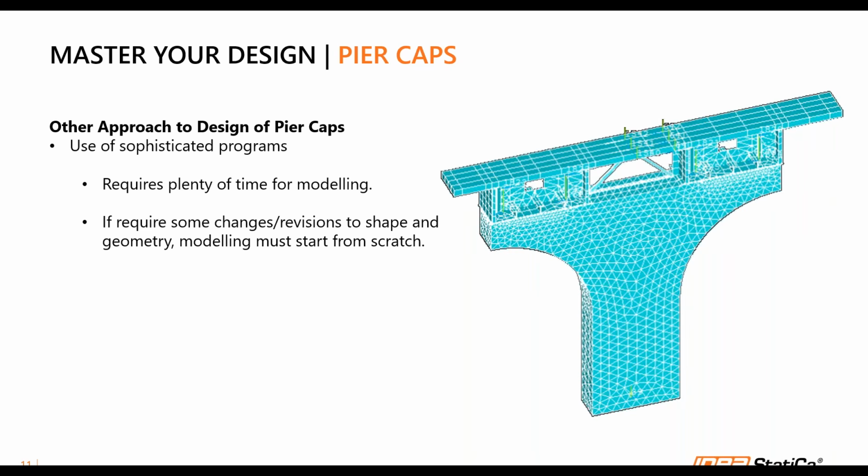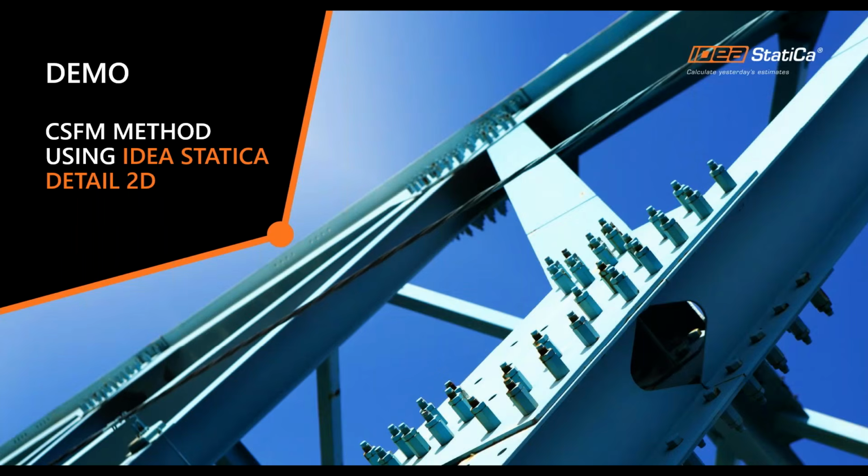And yeah, sometimes, if you have changes or revisions, for example to the shape and geometry, in some programs you may even have to start from scratch. So another alternative is the use of the CSFM method. In this demonstration, I'm going to show how to model and code check a Pier Cap using Detail 2D in IDEA StatiCa. We will model it together with a DXF file, as I mentioned earlier.